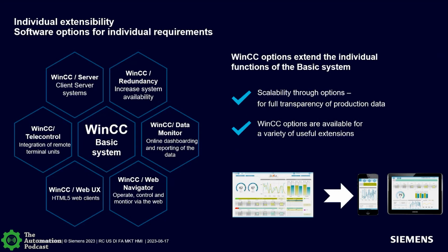Nice. So as opposed to having just 2 different systems out there in parallel running, talking to the PLCs, we've actually got a system that says, hey, I'll have one of you, the master, talking to the server. If I go down, communications automatically switches over to the backup, and lets you rebuild the master server. And then when you bring it back online, it'll slowly but surely rebuild all the data there, so you truly don't have any data loss. So that's a redundancy system.